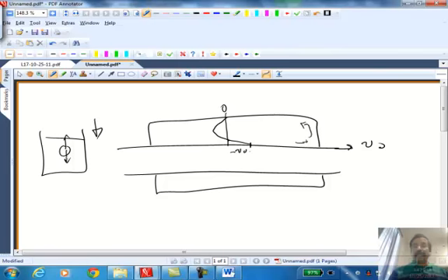The same idea applies when you have this that is being rotated and there is a cylinder there. Okay, so there's a sphere there. If that sphere is heavier than the fluid, then the centrifugal force, the weight that is throwing it out, should be dominant compared to the pressure force.